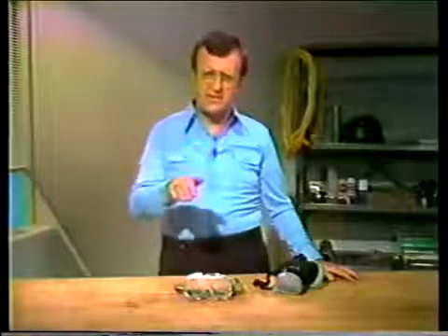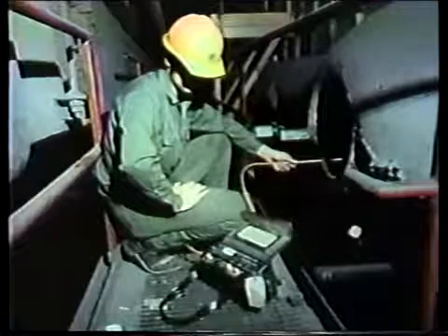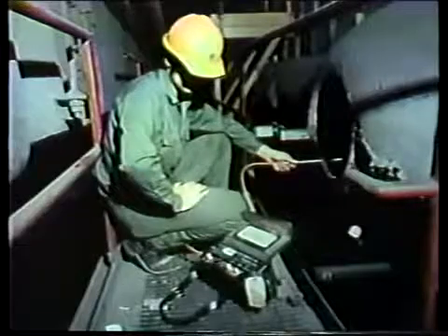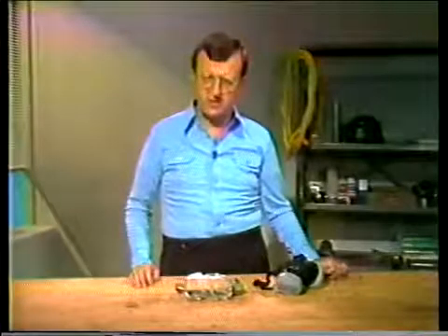During or soon after a chemical cleaning, it may be necessary to go inside a confined area in the boiler. A gas detector should be used to test the air inside confined areas in order to verify whether it's safe to enter them. Make sure gas detectors are available and working before you start cleaning.